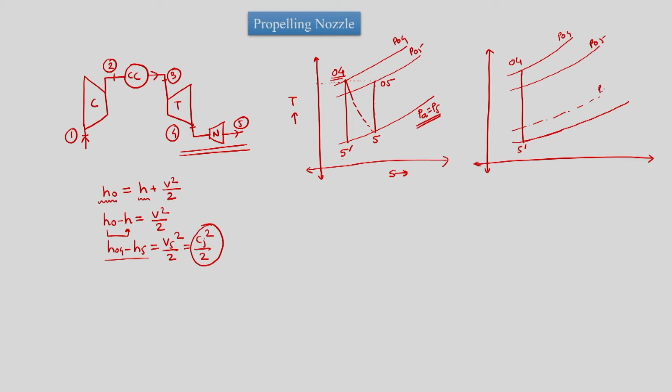However, it has crossed PC, which is the isentropic choking state. Since it has crossed the choking state, the pressure is further lower, and for us it is C dash.